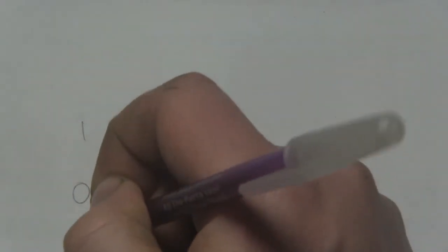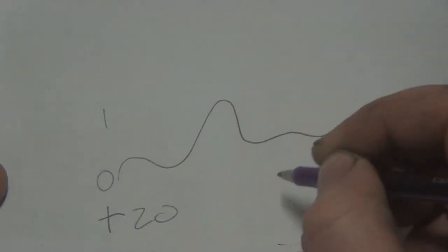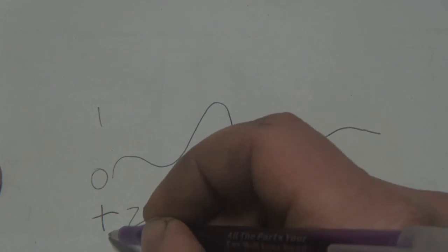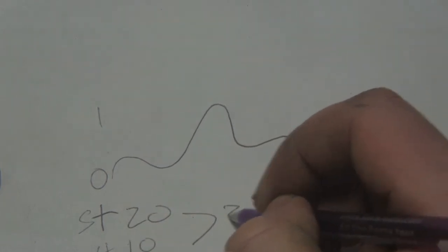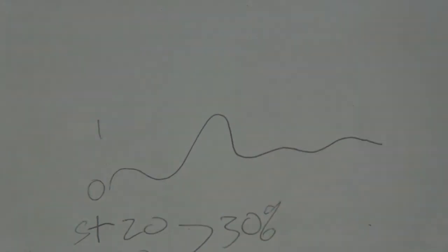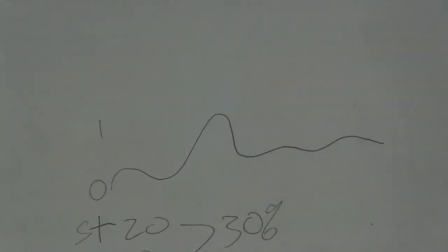So what are the fuel trims going to do in reaction to this? You're going to see fuel trims go positive. So we might see positive 20 on the fuel trim. So short-term fuel trim might be 20. Long-term fuel trim might be plus 10. We have an overall air-fuel ratio addition of 30%. How's that engine going to run? It's going to run terrible. Is it possible that it runs so rich it starts to misfire?